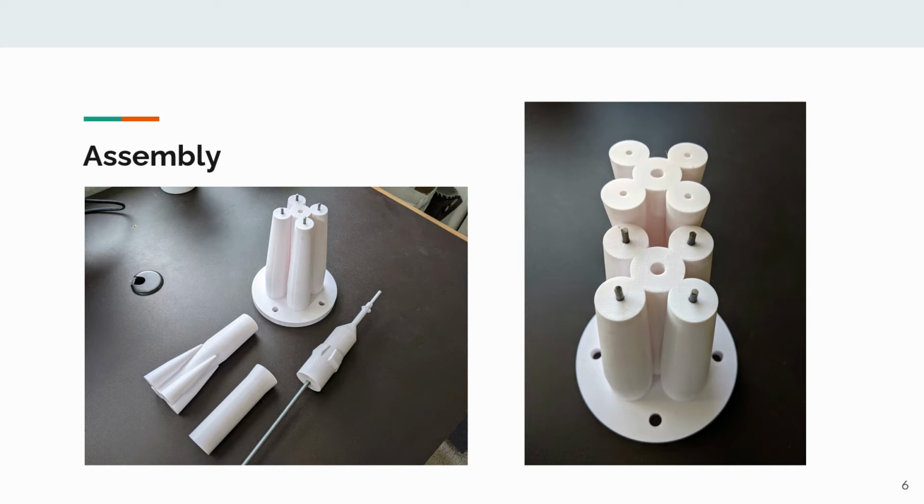Given that the interface between the first 3 top pieces are concentric circles, there was no need to worry about the alignment due to the symmetrical nature of the pieces. However, the base and the penultimate piece, which sport the asparagus thrusters, required an alignment technique to be developed. For this, 4 steel dowels were adhered to the base to serve as an alignment pin at the interface of the 2 pieces. Once assembled, the rocket is placed under tension via an inset nut and washer at the bottom of the base. Overall, this assembly method gave the model a rigid feel and proved to be successful during testing.